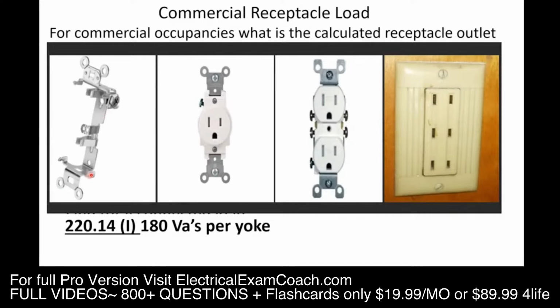What this code is stating is that whether we have a single, a duplex, or even this old school triplex here, each one of those would count as 180 VAs each. I like to think about it as each gang counting as 180 VAs. So if I have a single gang box, it's 180 VAs. If I have a two gang box and they're both containing receptacles on each side, it would count as 180 VAs per gang, and so on and so forth as you went to 3 and 4 gangs. Anytime you're dealing with a device strap, whether it has 1, 2, or 3 receptacles on it, it's 180 VAs per yoke.